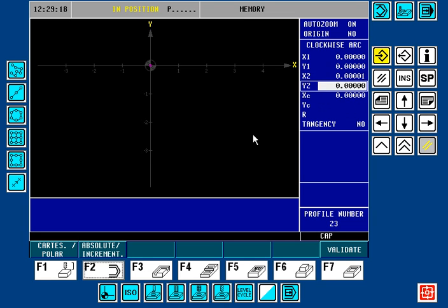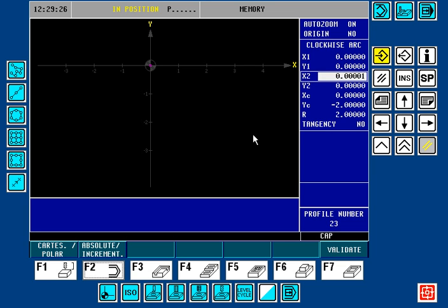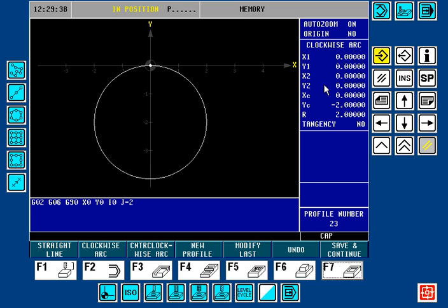So under these circumstances, when you run up against this issue, you will have no choice but to leave the x2 or the y2 as a floating value. So simply leaving it blank, allowing the control to solve it, and there it's recalculated it, given the information from the x-center and the radius, and the x2 is now 0.